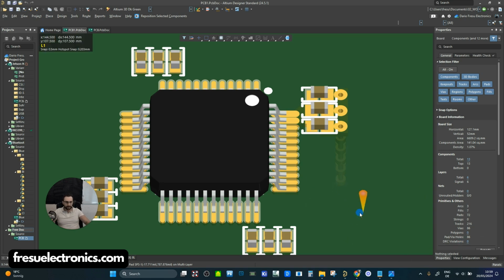So what is the best solution now that we can implement for our design? What is the best decoupling strategy that we can use? So first is, like we said, to calculate the target impedance. Then we choose the SMT capacitor package size. And finally, once we choose that, we can use the largest capacitance value available in this package size.